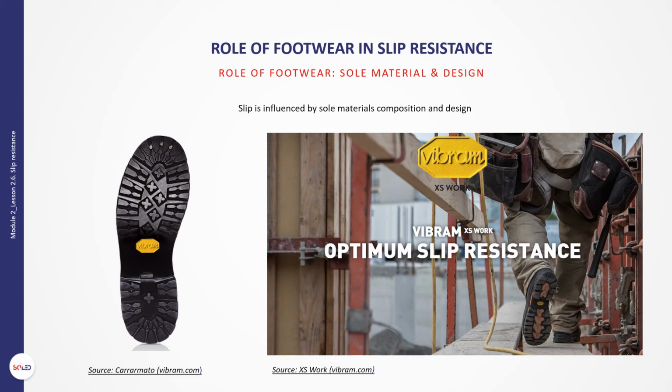Drainage channel. The recommended guideline is that the width of the channel of the outsole pattern shall be at least 2 mm, in depth within a range from 2 to 7 mm. The important function of the channel is to store the contaminant which is squeezed from the contact area, then drain the contaminant away from the sole bottom.